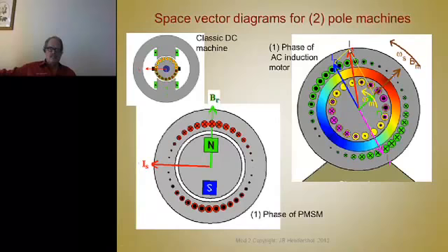There's the stator current. That consists of two vectors. One is the current it takes to magnetize, to create the B field, to magnetize the magnetic circuit. And the other vector is the current value that flows in the rotor to produce torque. And so both of those currents have to be supplied by the stator and by the power supply, by the power source. But what's interesting about this is that there has to be slip.